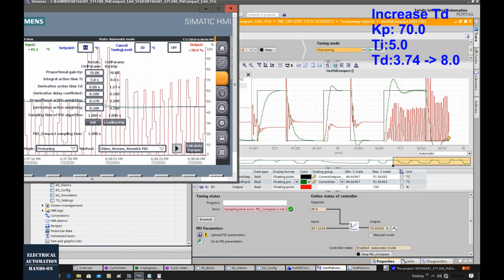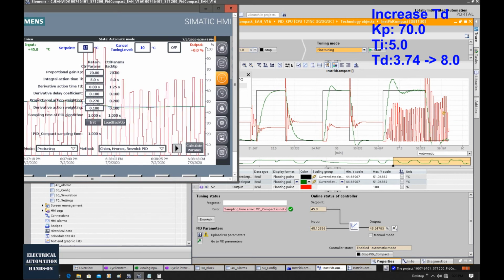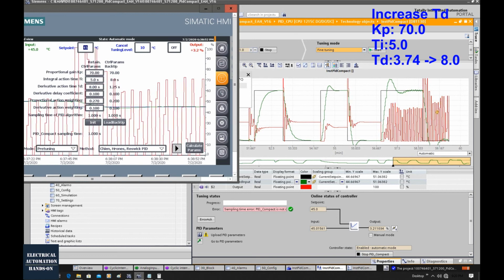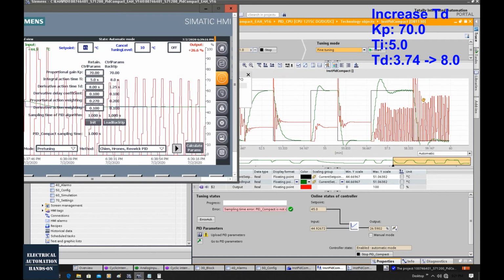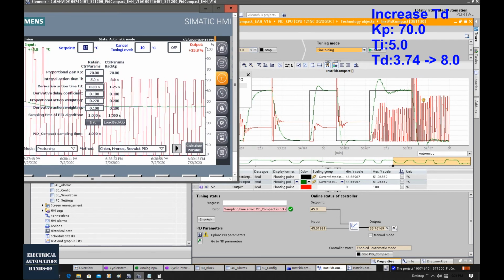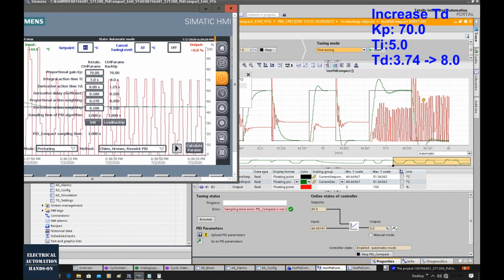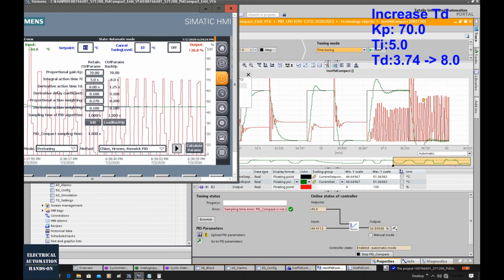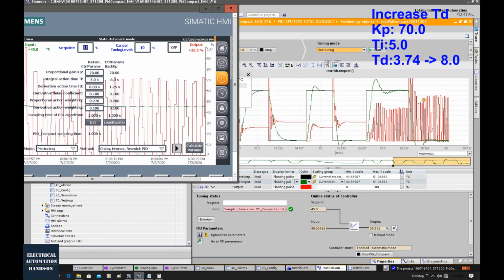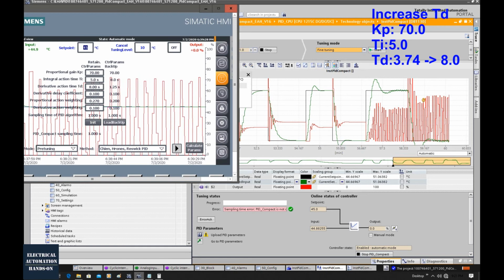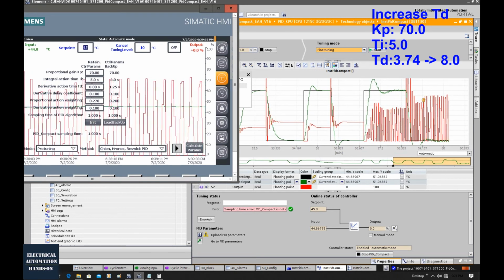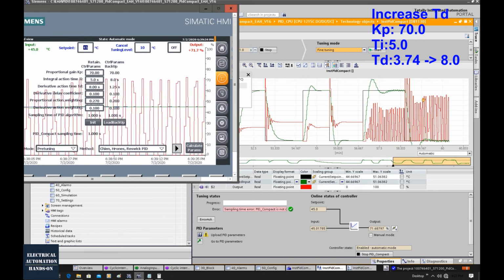Okay, from this following process, we will see this output control from the PID is very sensitive. Here it comes up one topic. In some plants, after the process starts running for 1 or 2 years, the maintenance team will find the actuator and the valve controlled in this PID loop will wear out and become defective very soon.